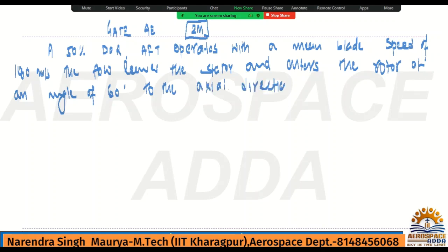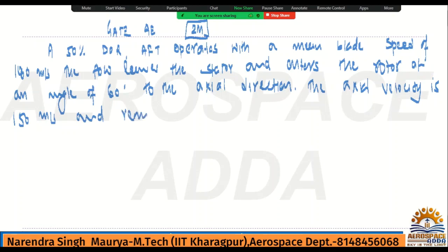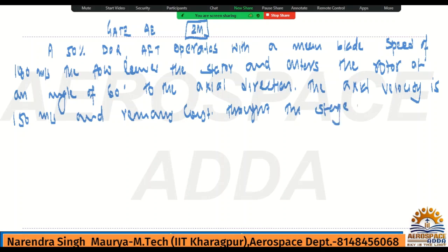axial direction. Last lecture I had explained AFT, axial flow turbine, so based on that, a 2 marks question is asked. To the axial direction, the axial velocity is 150 meter per second, and remains constant throughout the stage.